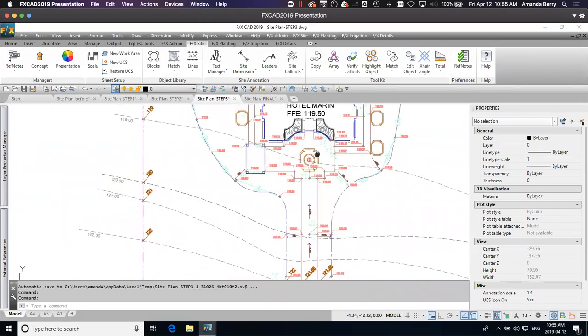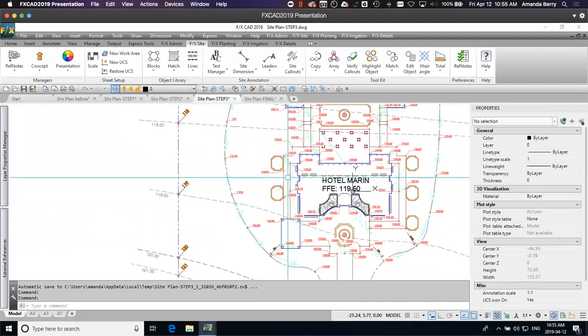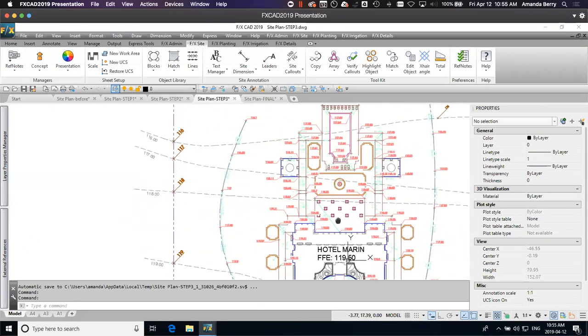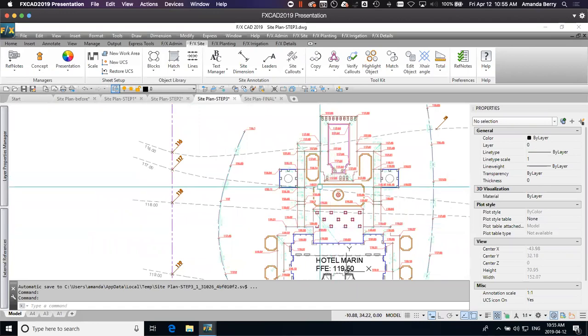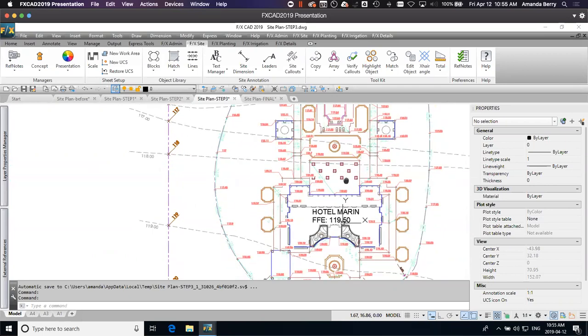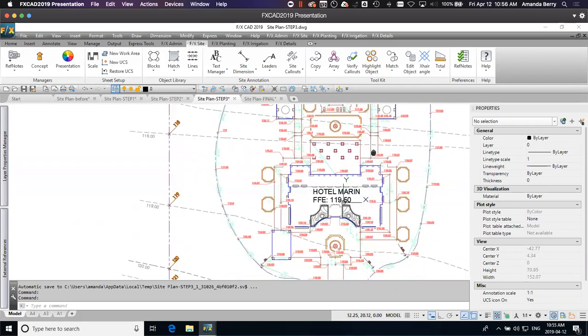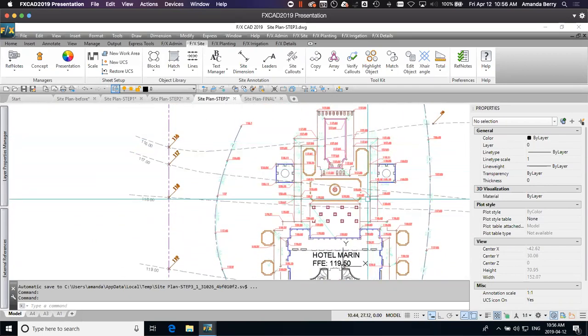So if you just have a little area like this, sheet flow across a walkway is absolutely fine, I find. But if you're getting a lot of drainage, you want to start considering swales on the one side of a pathway in order to limit the amount of water that would sheet flow across it. So those are just some design considerations.